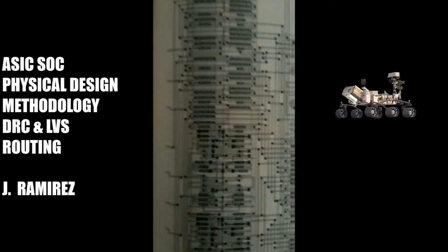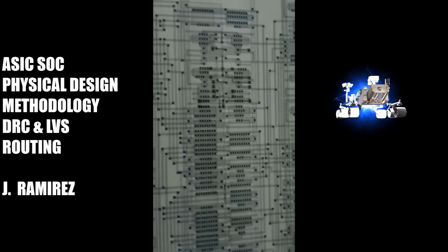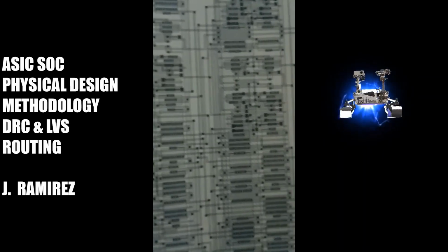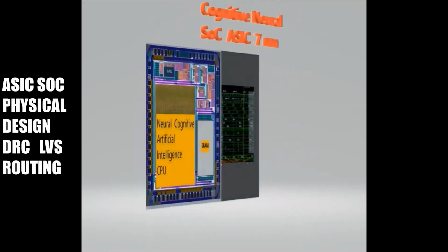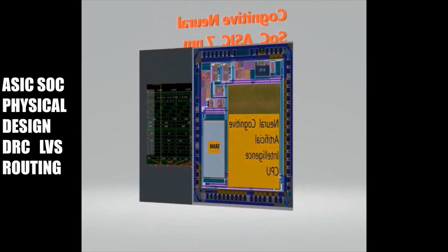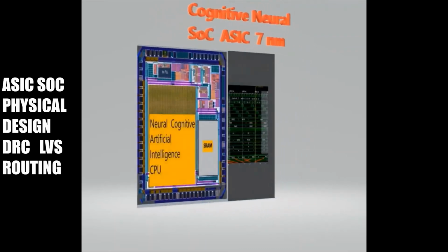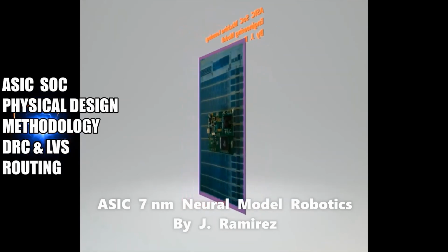The DRC is performed at two levels, since the detail router normally works with logic cell phantoms. The first level is a phantom-level DRC, which checks for shorts, spacing violations, or other design rule problems between logic cells. This is principally a check of the detail router.